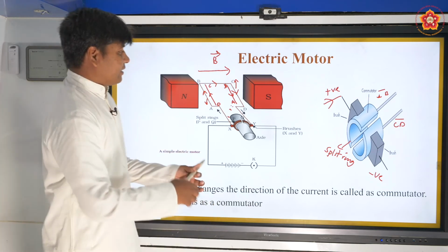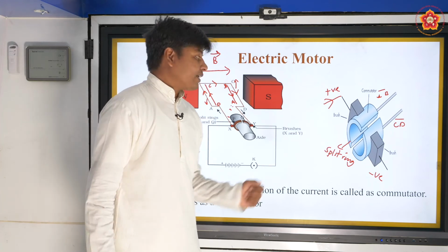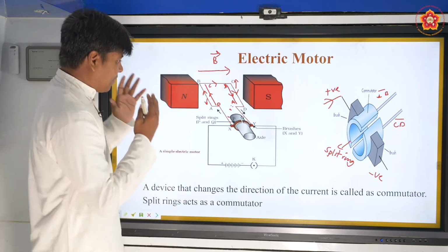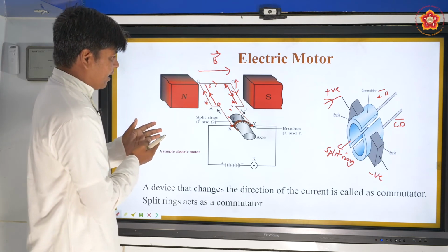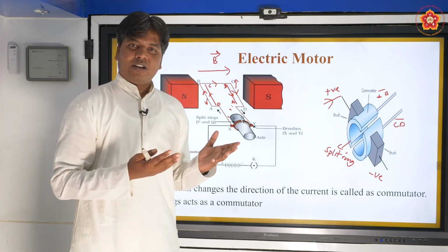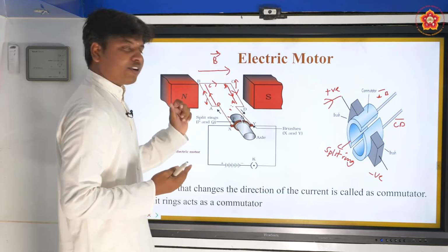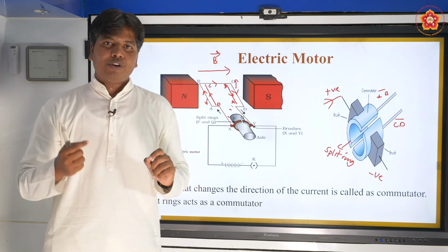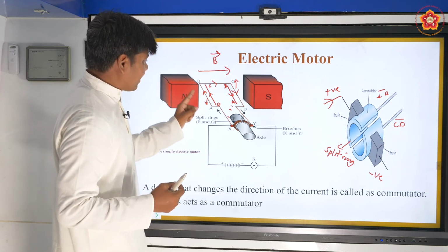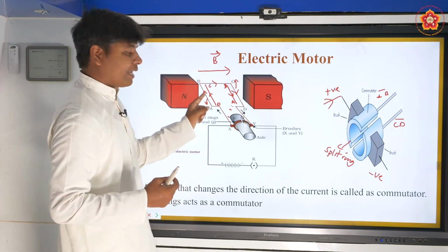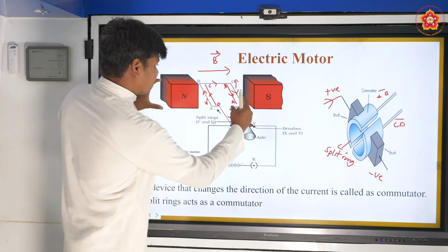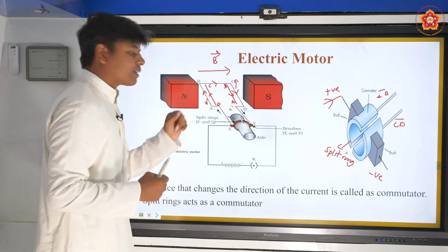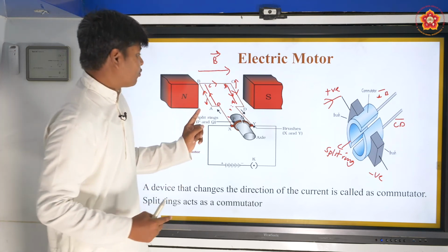See, this is an ingenious device, and this whole setup is very ingenious, right? Because I am passing electricity and it is rotating. Nobody is manually going there and rotating. By passage of current, and we know the current carrying conductor produces a magnetic field around it, and you have an external magnetic field, both together give rise to a force on this conductor which tries to move it.